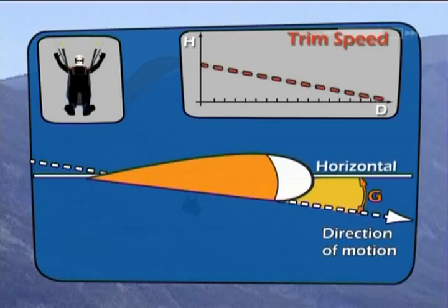When learning, the main reason for flying at such a speed is to accelerate before landing and build up energy that will eventually be converted into a flare. This makes a soft landing possible. Flying at trim speed also reduces the likelihood of problems caused by the wind gradient, such as inadvertent stalls or sudden altitude loss near the ground.